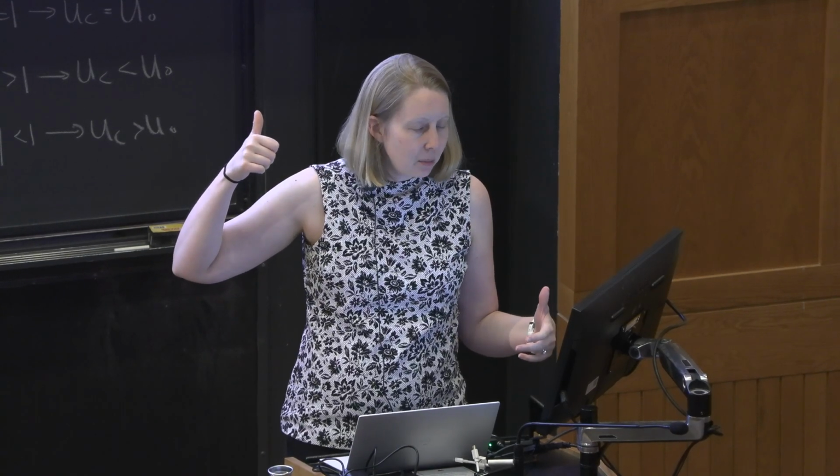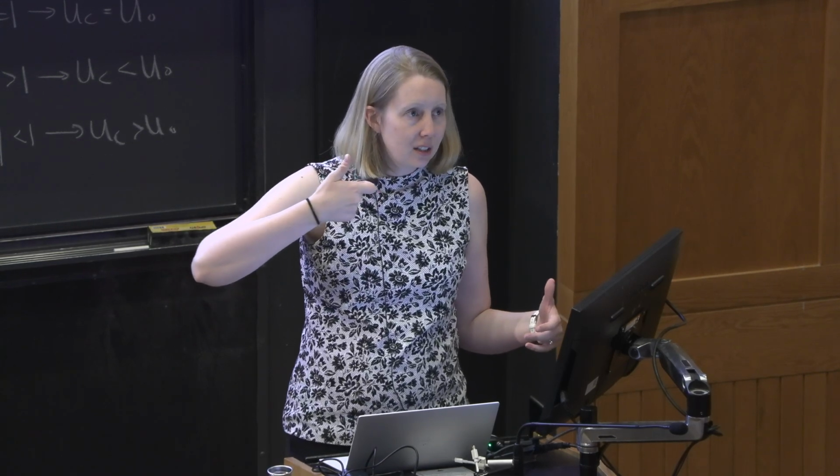Other questions? Yeah. I don't quite understand how the damping part works. Because it has a specific frequency, there's a destructive interference. That's what damping is. Oh, yeah, sorry, I didn't talk about that. It sucks acoustic energy out. So if you're putting so much energy into the acoustic field from the flame, and you're resonating another part of the system that has nothing to do with the flame, you're taking some of that acoustic energy out of the system and spending it in that resonator.